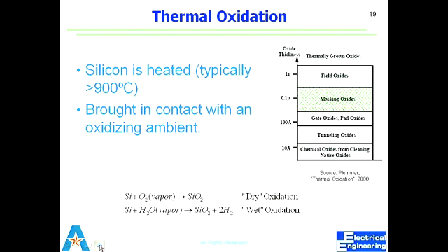But if the thickness goes high, for other types like field oxide and masking oxide, what kind of oxide will we grow? Wet oxide. And native oxide is something which is very, very thin.